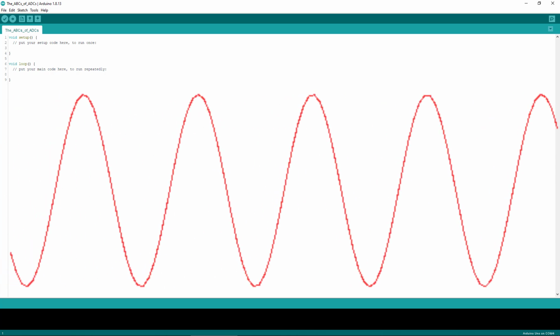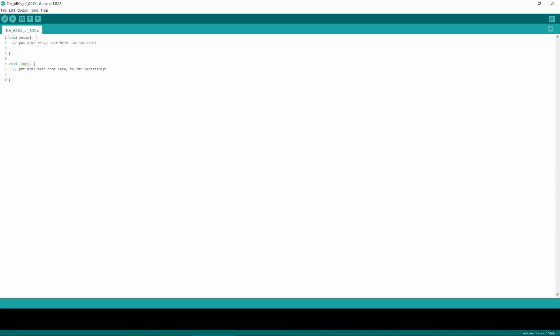Analog signals continuously vary with time. So to convert an analog signal into digital form, an ADC must sample the analog signal at a certain rate or frequency. By sampling, we simply mean that we need to check the level of the analog signal every so often, whatever our sampling rate happens to be. And this sampling rate is governed by the Nyquist Theorem.